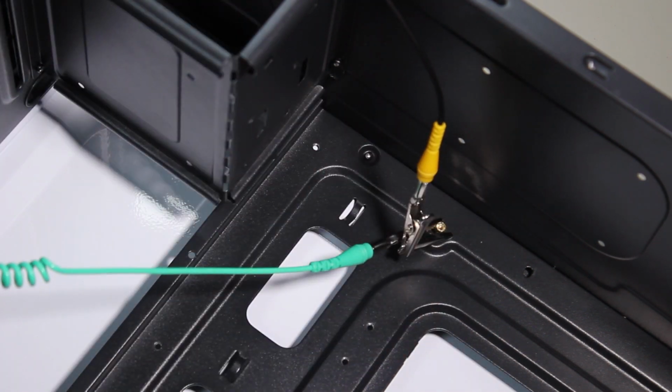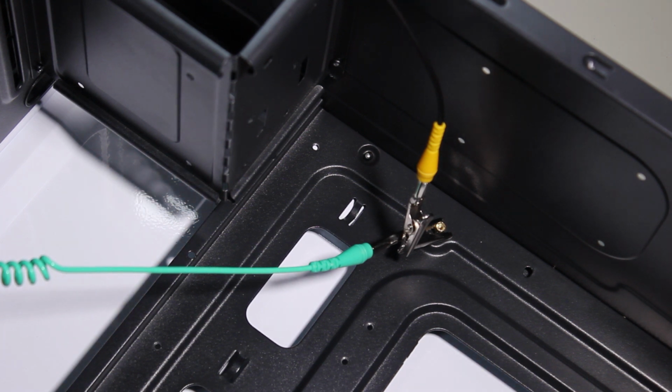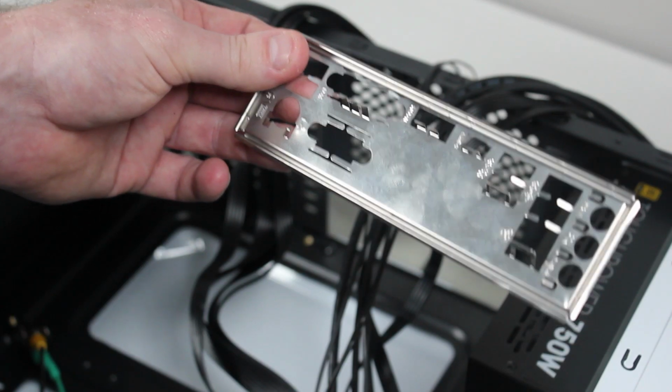Even if you don't have an anti-static mat, you can still attach your anti-static strap to the computer case. Although it is not ideal to work on a computer without an anti-static mat, the computer case will be able to collect some static electricity. There is some debate about leaving the power cable in to ground the computer and switching the power supply off, but this increases the risk of electrocution if something was to go wrong. So general best practice is to unplug the computer when working on it, even if you don't have any anti-static mat or equipment. The first step to installing the motherboard is installing the I/O shield.